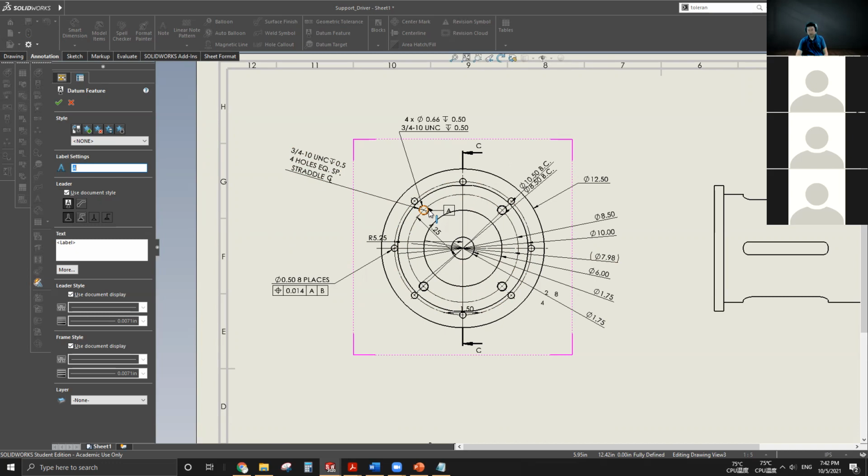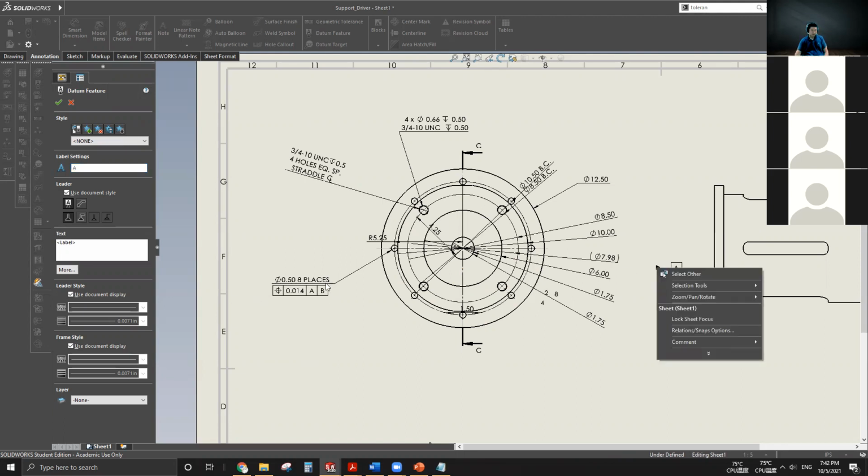And when you set it up on the milling machine, it needs to be fixed from a certain coordinate. Then they can use the dimension and the tolerance of the positioning of this hole to locate the tapping point, and then they can tap it from there, right?